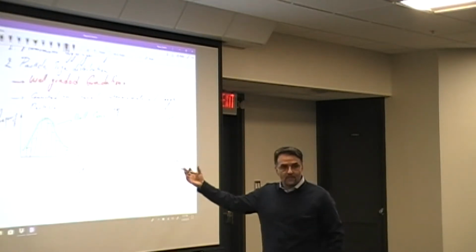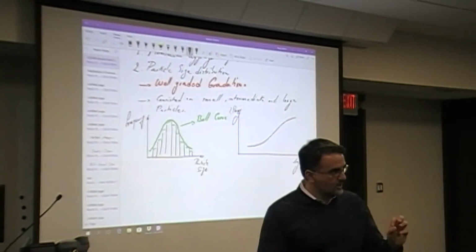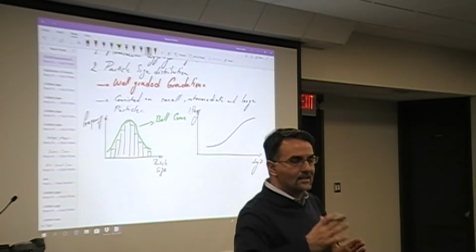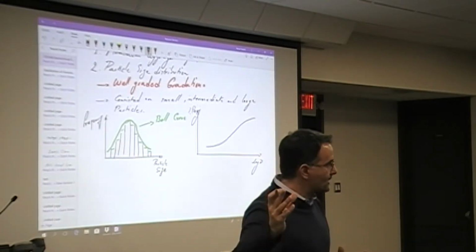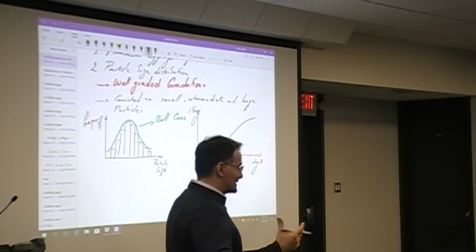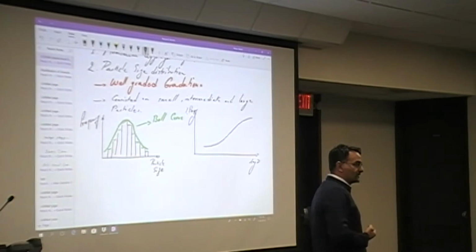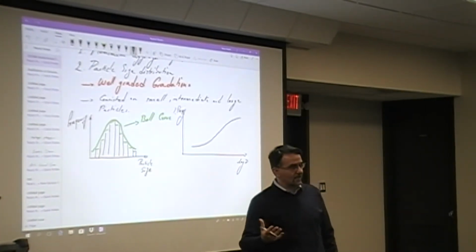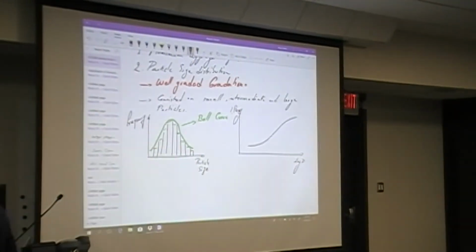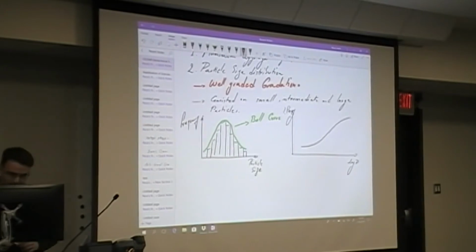So what happened here, since I was able to pack more small particles in between the large and intermediate particles and more intermediate particles in between the large particles, now I maximize the particle contacts, right? So now that you have the higher particle contact, you have better interlocking effect and you have better frictional forces there. Therefore, your load transfer mechanism is going to be a whole lot better there. All right, so this would be the case for the cumulative distribution that we have here.